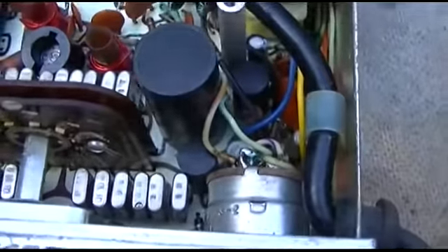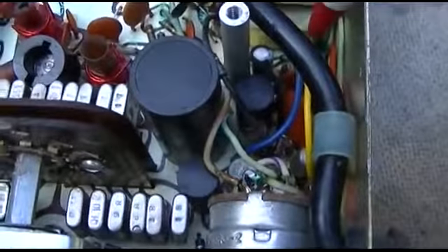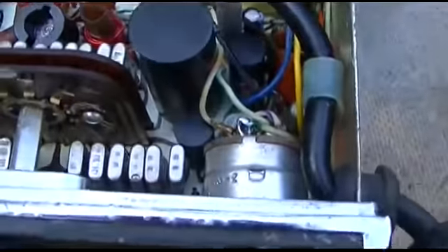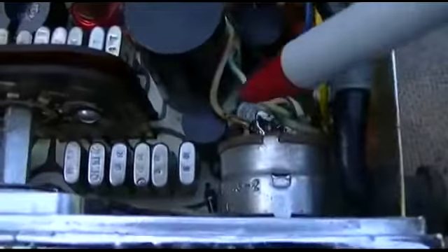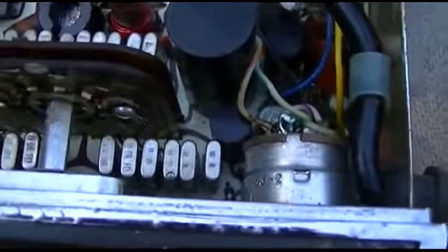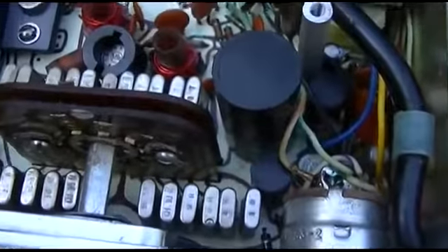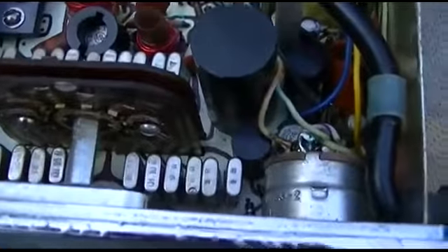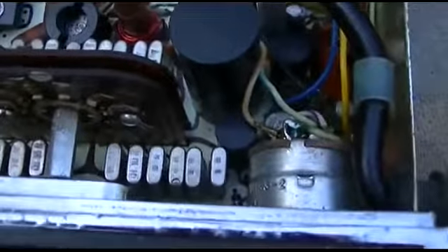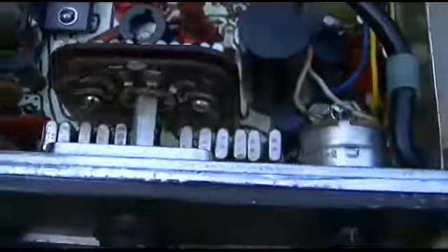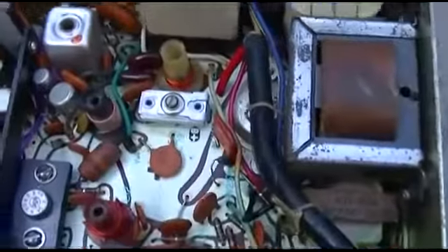I want to say a cathode, but it's like a collector bypass cap, because this is PNP germanium. I checked all of the rest of them and they were actually okay, and when I say okay, they weren't that leaky and they weren't insufficient. If anything, they were overvalue. Just not going to spend a lot of time on it because it's not something I'm going to use.